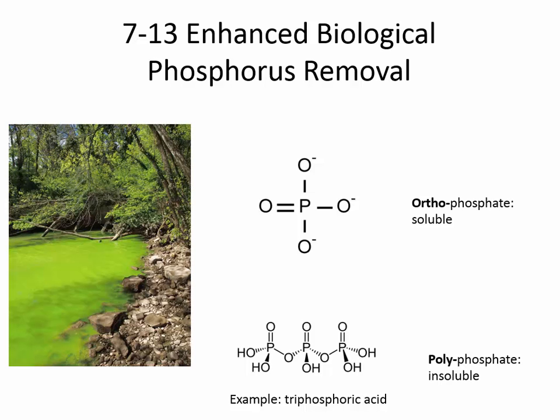The water's not supposed to be black. And they'd think it's polluted water, but really all it was just iron or manganese. And so the objective of adding a little bit of orthophosphate was to keep the water softened and just to tie up the minerals.